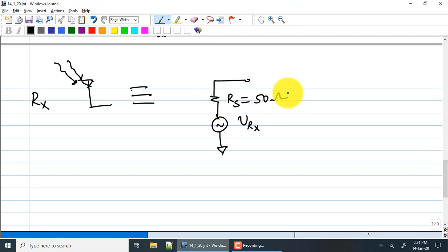For some reason the standard impedance for all electromagnetic components for wireless applications is 50 ohms. So if you are doing anything related to microwave circuit design, everything is referenced to 50 ohms. In our case, inside the integrated circuit, we have the option of choosing any impedance that we want.